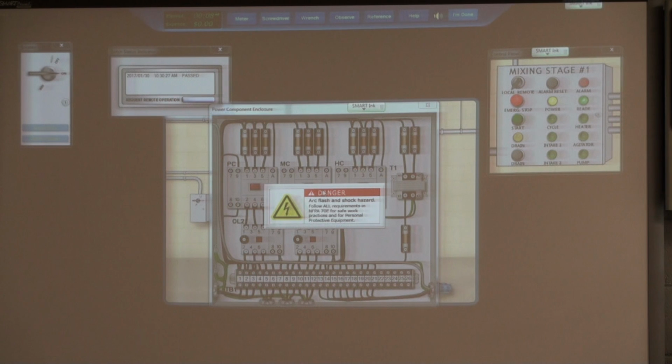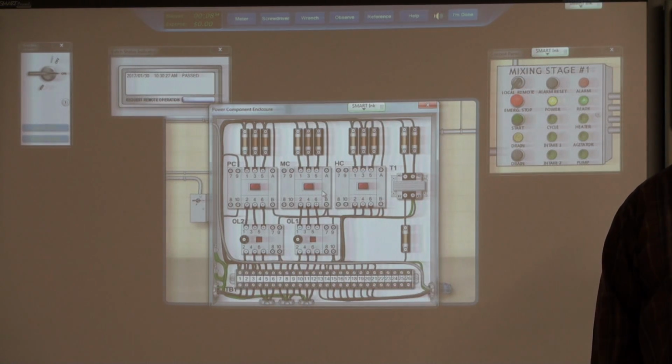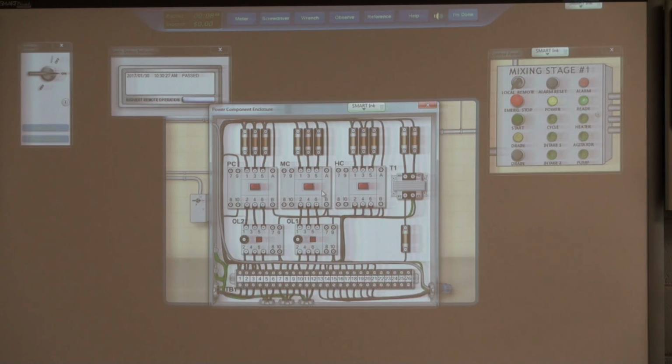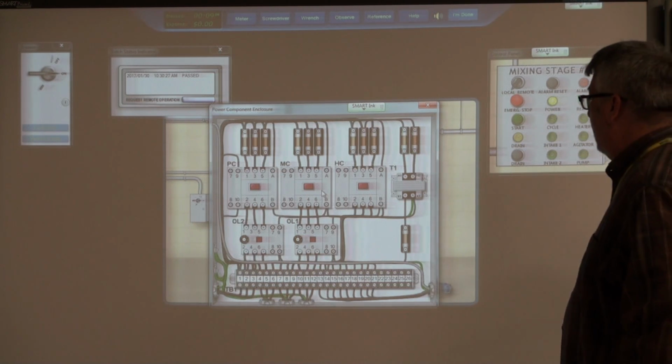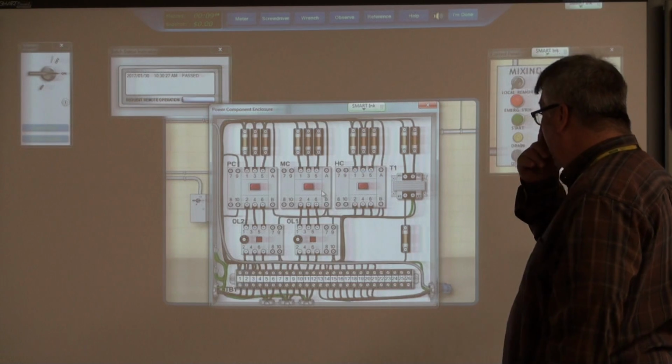We'll go over here and apply the key. Arc flash and shock hazard. So better not measure any of this on ohms with power on. No, because it'll kick you out of it right quick, I promise you. It won't penalize you for opening it. It'll penalize you if you put an ohm meter on with power on. It will definitely tell you to come back later.